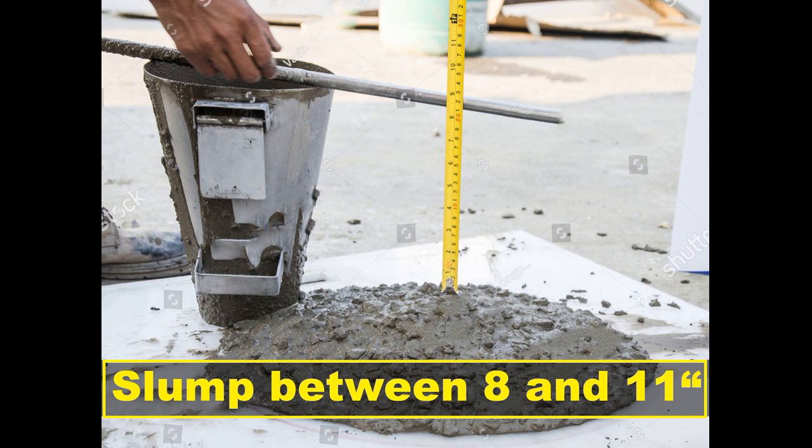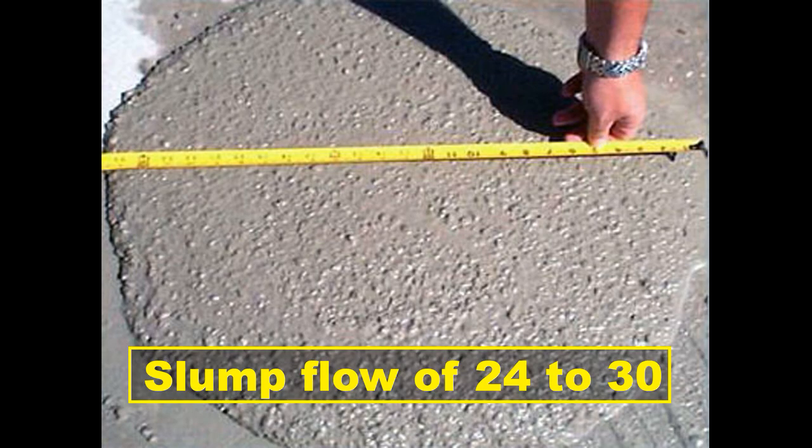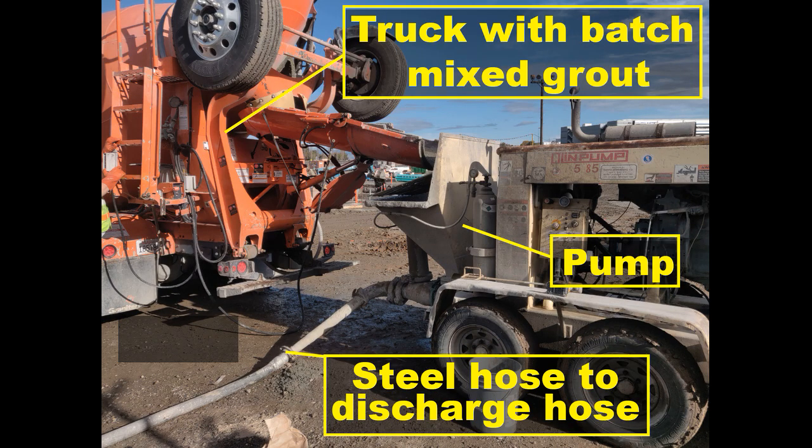Ready mix grout. Use conventional grout with a slump between 8 and 11 inches. Use self-consolidating grout with slump flow of 24 to 30 inches. Provide minimum grout strength of 2,000 psi in 28 days, as tested in accordance with ASTM C1019.